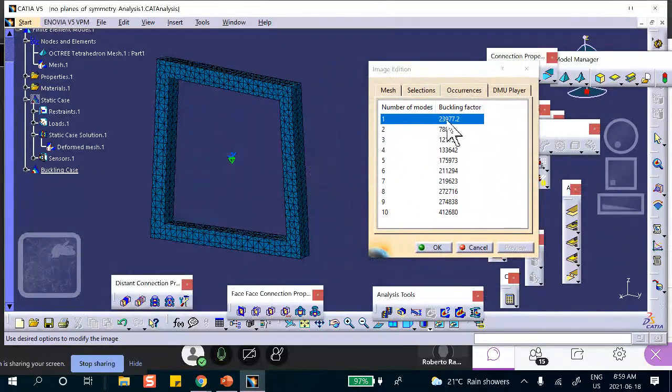And it shows you the buckling factor, multiplied by 1. Remember the one that you applied, that P that you applied? You're going to get the different buckling loads. For example, this mode will buckle at, whatever, that unit was 1 pound, right? 1 pound times this, at almost 24,000 pounds, and it will buckle like that.